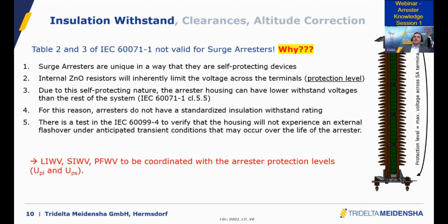But in theory, if the calculation of the protective distance is done properly, you should be able to have the same withstand level for the rest of your equipment in the substation as the arrester housing. But this needs to be checked, of course, because it will depend on the installation distance from the equipment to the surge arrestor.